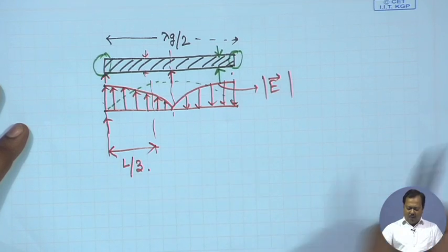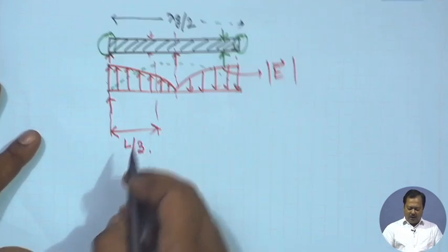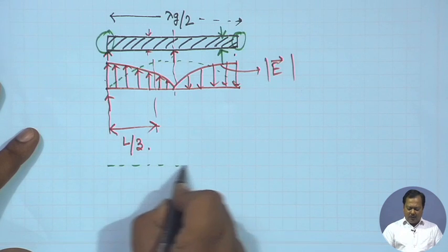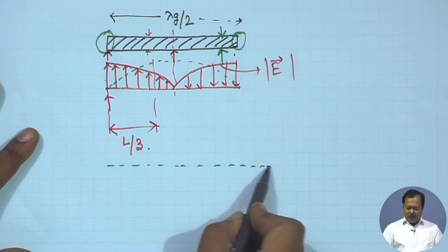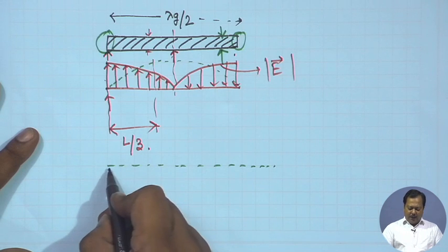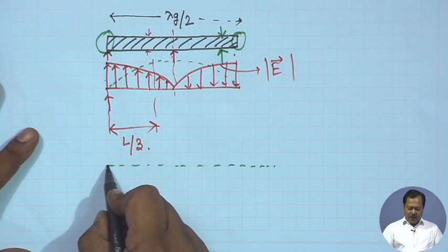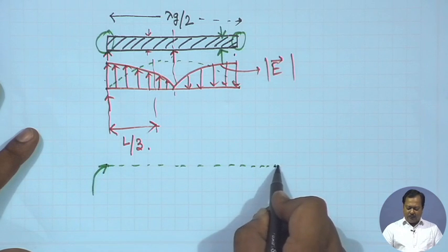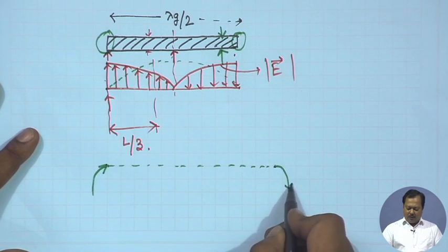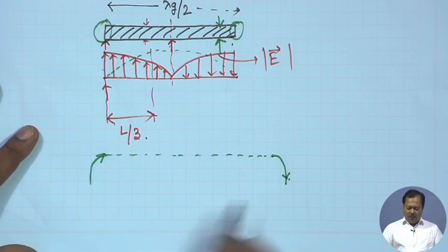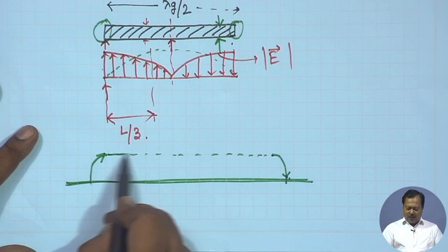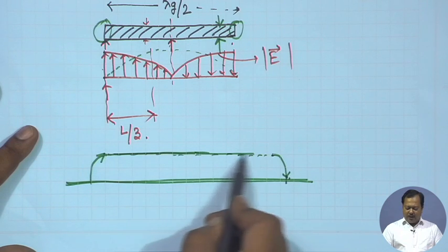Now, how do we have radiation from the fringing field? Obviously, for that, the electric field and magnetic field have to be in the same phase. So, let us say this is the fringing field components. I am drawing the side view. At the bottom we have the ground plane, and this is the top plane strip.